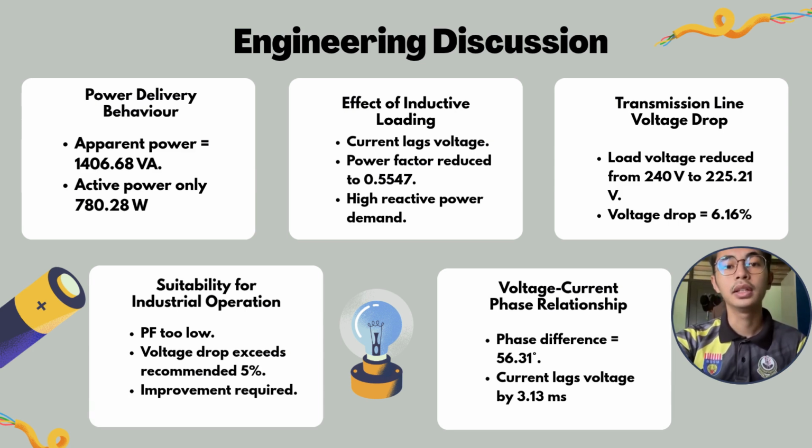The system delivers 780.28 watts of active power, but also carries a large amount of reactive power, showing that not all supplied power is used effectively. Overall, the system operates successfully, but its low power factor and voltage drop make it less suitable for long-term industrial operation. Therefore, power factor correction and voltage regulation are recommended.